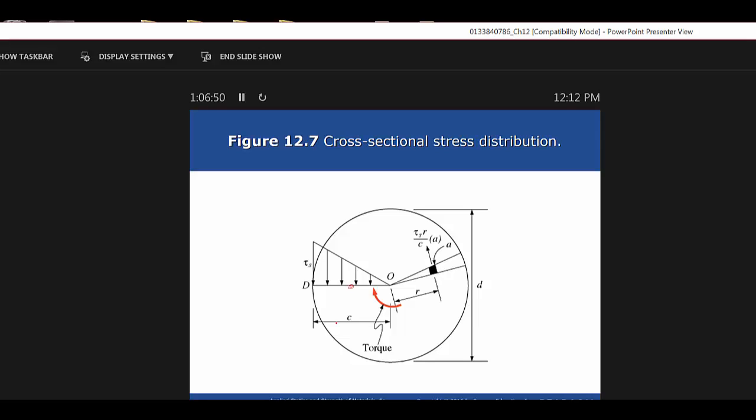Max shear stress is basically the same thing here. The only number that changes is the polar moment of inertia, because it's still a 4-inch diameter outside. The only way that number is going to change is if we said the diameter is 3 instead of 4, then your number at the bottom, that 2, would then be 1.5, wouldn't it? That's the only thing there. And let's see, what else does it say there now? Oh, that number ended up being